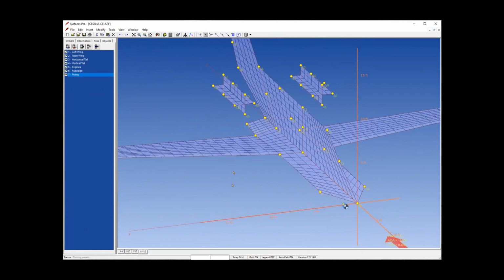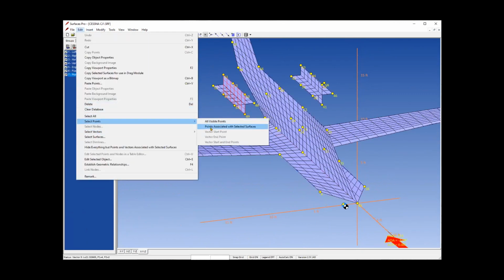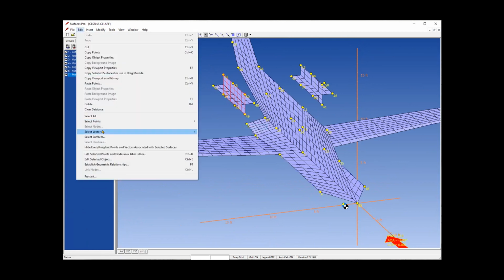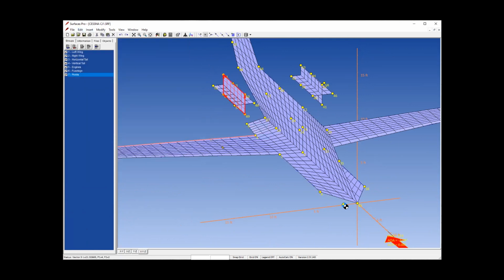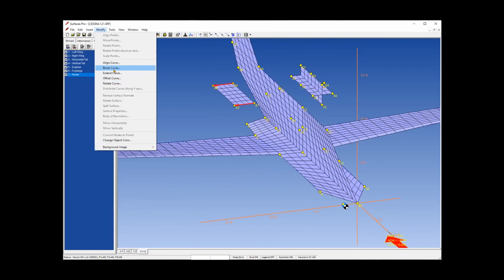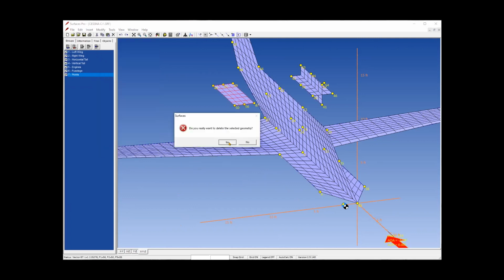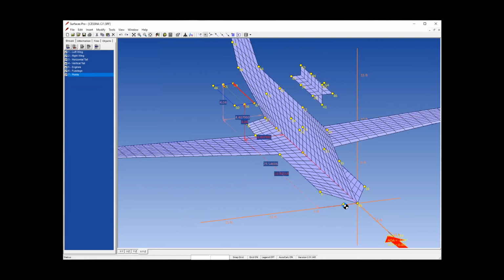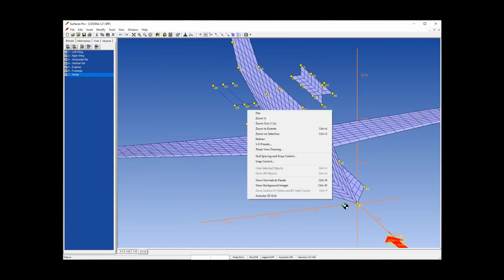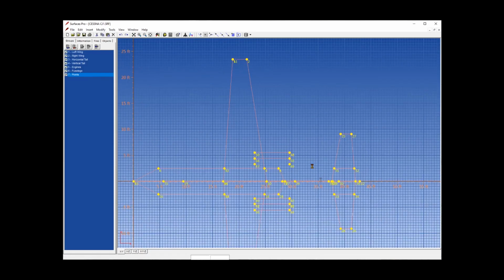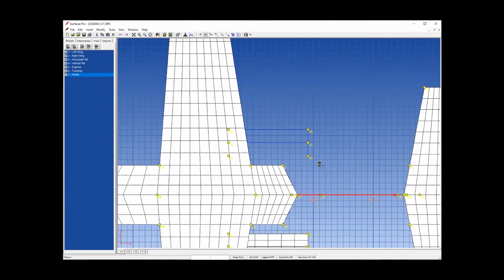Let's modify its nacelles to the new form. Here we see the nacelle is of the simpler kind. Let's delete the vertical wall. Then let's split the B1 and B2 vectors. Then delete the horizontal surface. Reconnect the input vector to the new center points. And delete the input vectors and points.